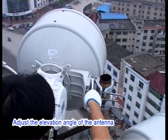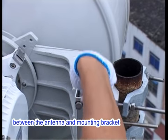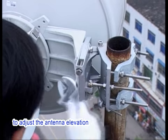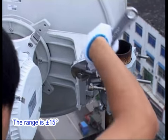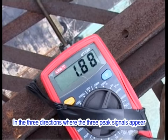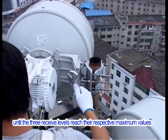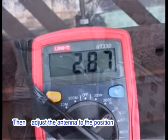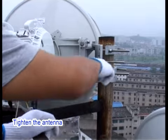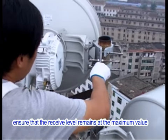3. Adjust the elevation angle of the antenna. Properly loosen top and bottom connection bolts between the antenna and the mounting bracket. Rotate the elevation adjusting bolts to adjust the antenna elevation. The range is -15 degrees to +15 degrees. In the 3 directions where the 3 peak signals appear, adjust the elevation angle of the antenna until the 3 receive levels reach their respective maximum values. Then adjust the antenna to the position where the receive level is the highest of the 3. Tighten the antenna. When you tighten the antenna, ensure that the receive level remains at the maximum value.